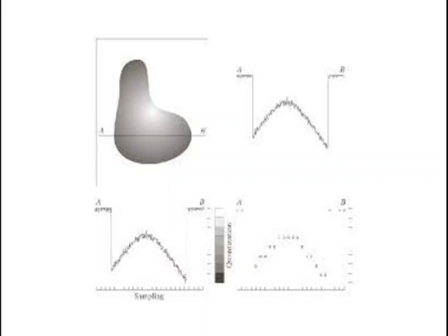When a sensing strip is used for image acquisition, the number of sensors in the strip establishes the sampling limitations in one image direction. Mechanical motion in the other direction can be controlled more accurately, but it makes little sense to try to achieve sampling density in one direction that exceeds the sampling limit established by the number of sensors in the other. Quantization of the sensor outputs completes the process of generating a digital image.